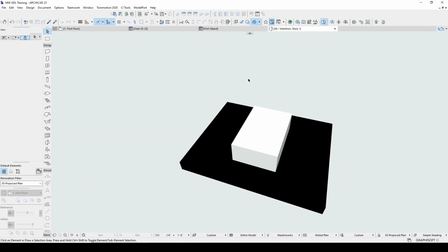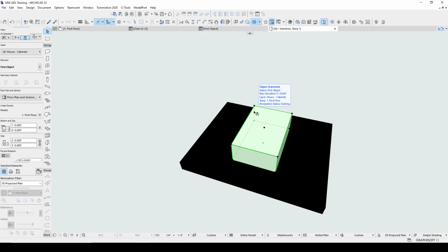And this is one of the most powerful parts of ArchiCAD, is recognizing that we often want a symbolic view of an object coupled with a 3-dimensional representation. There is also a way to do a projection, which I'll show you later, so that the 2D view for complicated objects is created automatically. But in general, it's better to directly control the 2D view through coding.